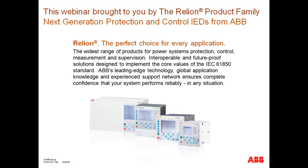As part of Edition 2 of the standard, this is something that has been defined, the sending and receiving of signals from 2 substations that are geographically remote, or 3 substations, or 4 substations that are geographically remote, for transfer tripping and for teleprotection type signals. It's actually something that is common and is indeed done utilizing GOOSE messages. Okay.